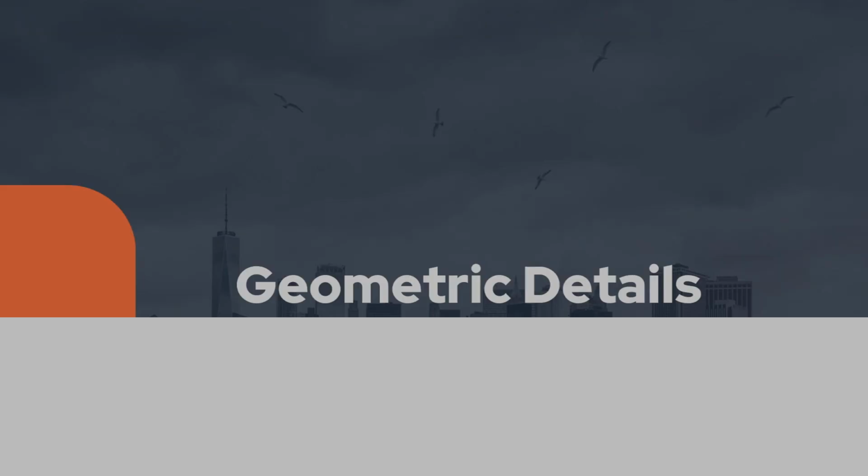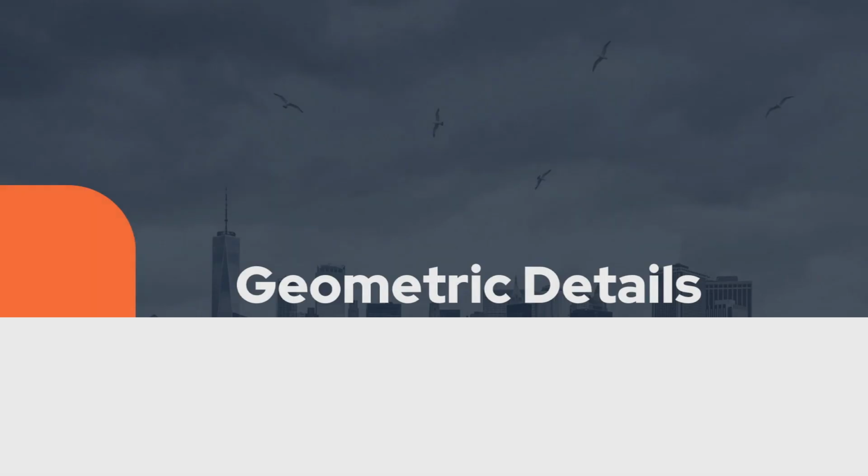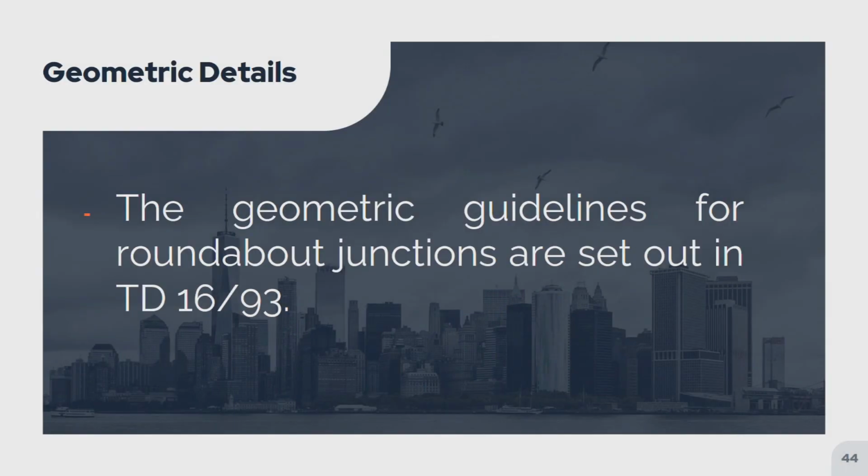When analyzing the capacity of a roundabout intersection, the capacity of each of the entry arms is assessed and compared with the traffic flow expected at peak hours within the design year. So geometric details. The geometric guidelines for roundabout junctions are set out in TD 16/93.